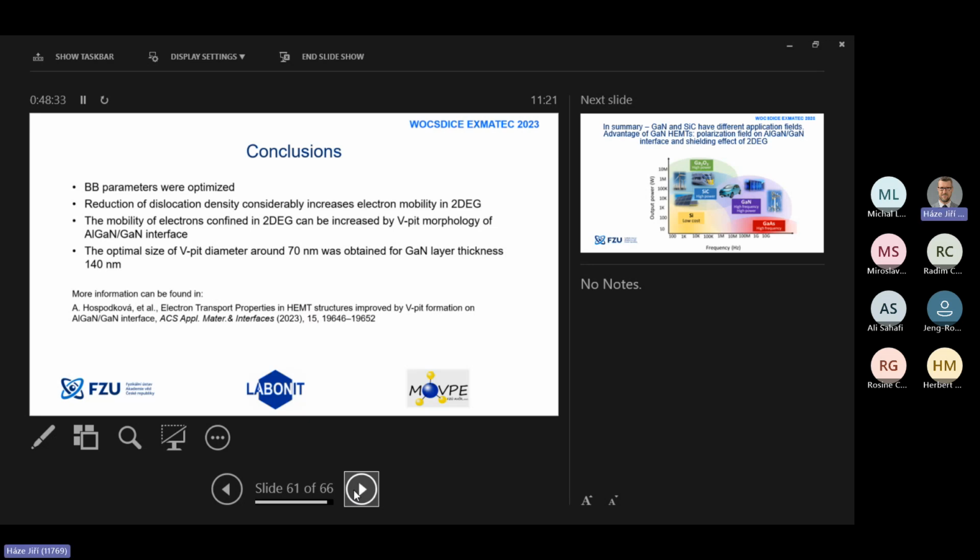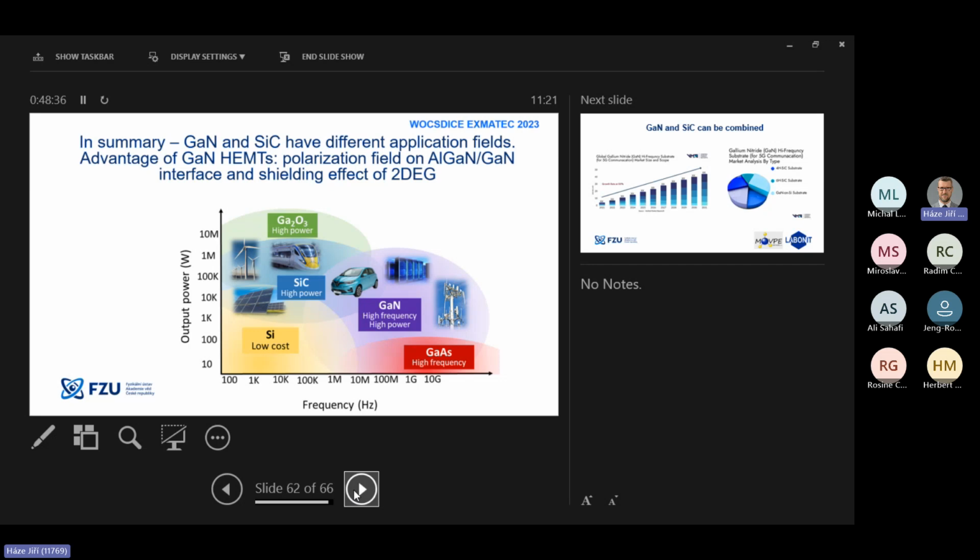And to say in a summary, I would say that silicon carbide and gallium nitride are not competitors. They are more semiconductors for different applications: GaN for high frequency, and also for high power. Silicon carbide, because it has its own substrate, is perfect for higher power applications, high voltages. I hope they can even collaborate, by growing one on top of the other.